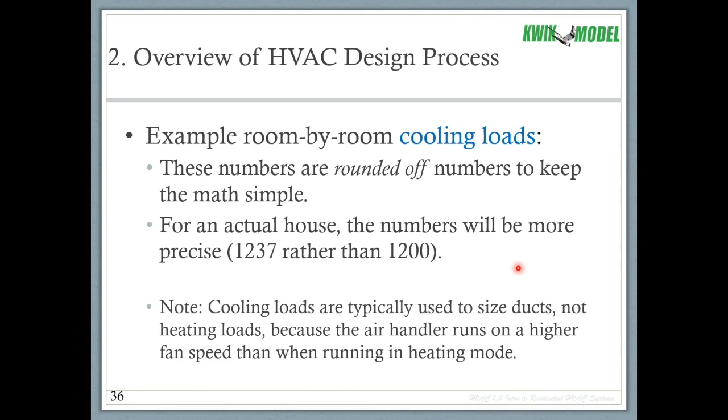And it will typically run on high speed for cooling and then one of the lower speeds for heating. That's very common and very typical. So if you're moving more air in cooling mode on high speed, that will generally drive the size of the ducts. But as we'll mention in a later slide, occasionally in an individual room, the load might be such that it needs a lot more air in heating mode than in cooling mode, and you might have to size the duct for that slightly higher airflow for heating than for cooling, but we'll talk about that more.